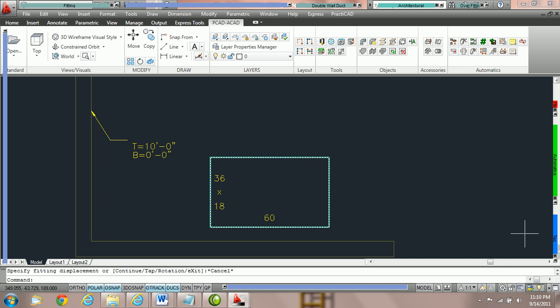However, this time if we go to do an elevation tag or just look in the elevation box, you can see that the bottom of the duct is at 15 foot high. So we've done it correctly. So this is how to use your replace Z command in AutoCAD options.